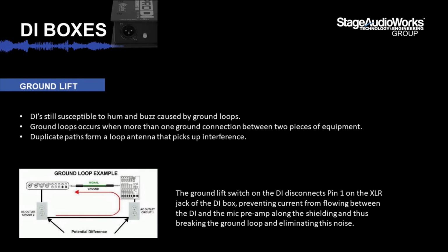A ground lift switch is often seen as well on a lot of DIs. So even though DIs do a great job of eliminating external noise in unbalanced line level instrument signals, even balanced audio equipment is susceptible to hum and buzz caused by ground loops.